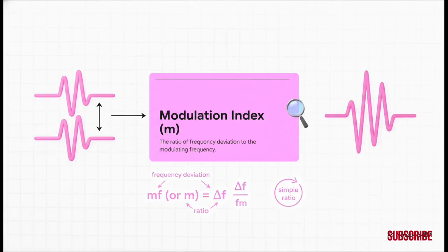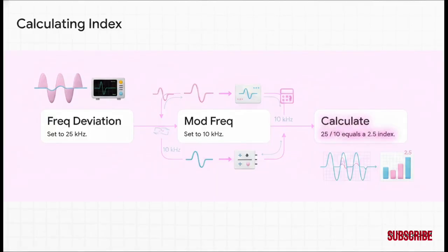Now, circling back to that mystery variable MF, or simply M, the modulation index of FM. To find our modulation index, we just take that frequency deviation we calculated, delta F, and divide it by the modulating frequency, FM. It's a really simple ratio, but it tells us exactly how heavily the carrier is being modulated. Just to cement this concept, if a system has a 25 kHz frequency deviation and we divide it by a 10 kHz modulating frequency, boom, it gives us a very clean modulation index of 2.5.